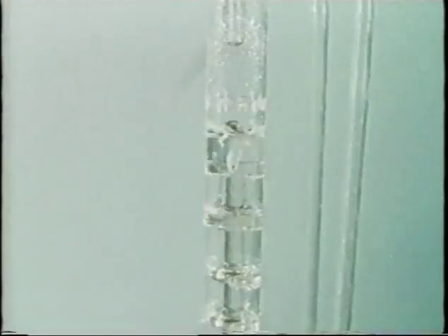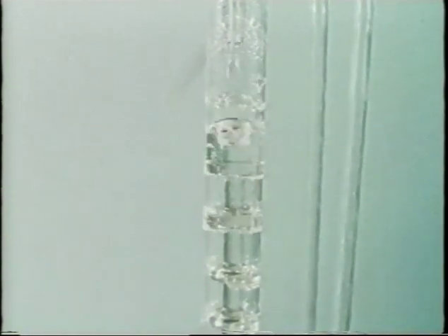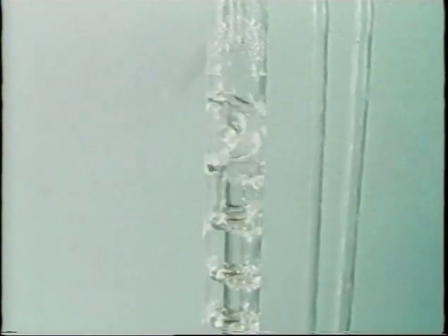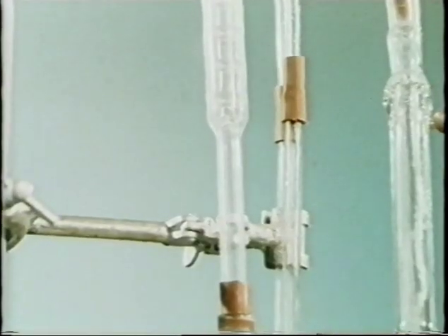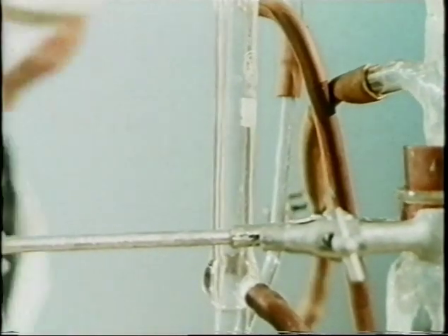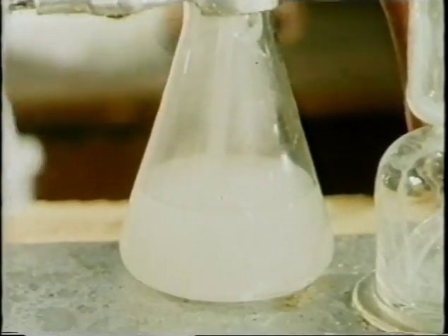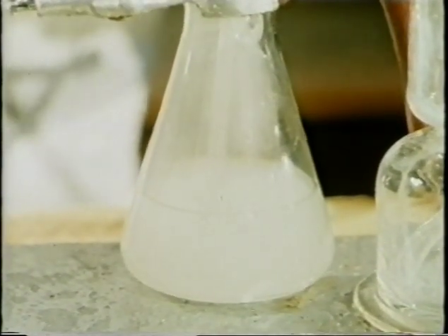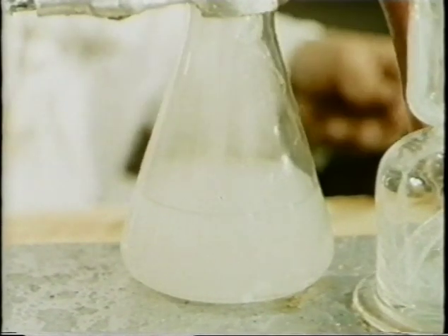Blown up the column, it meets the ammoniated brine. Carbonation takes place with the formation of ammonium carbonates. Condensers are fitted corresponding to the cooling boxes. The solution at the bottom is mainly ammonium carbonate and sodium chloride.